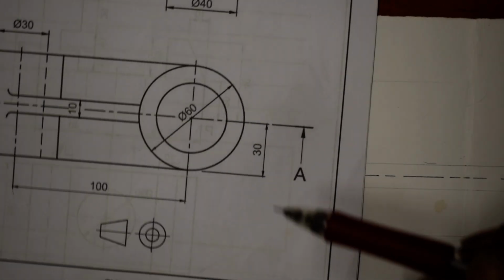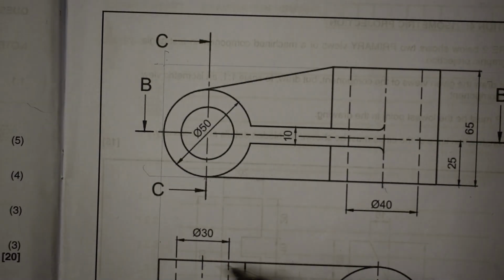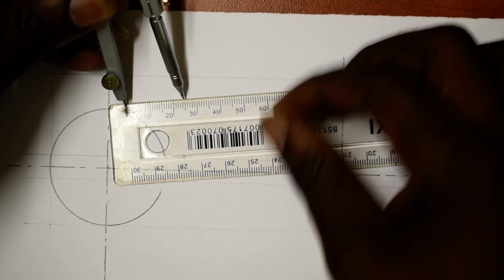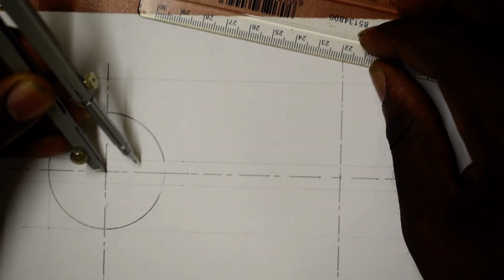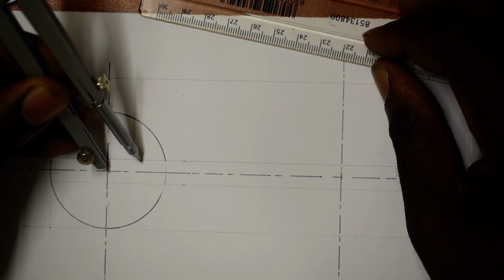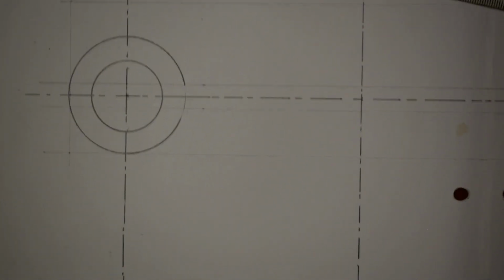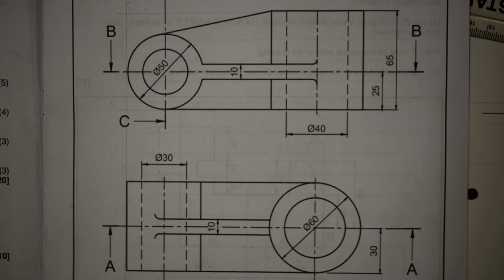Okay, so from here I have another diameter. So another diameter inside. We are told what that diameter is, diameter 30. You get it? So how do you draw diameter 30? Take your drawing compass, place it at 0. Then open it to half of 30, which is 15, radius 15, so that I draw diameter 30 and draw it solid. You can draw it solid, this one. Then from there, what is going to happen now? So we are going to draw these views simultaneously. You get it? We are going to draw these views simultaneously, so that you make our work simple.